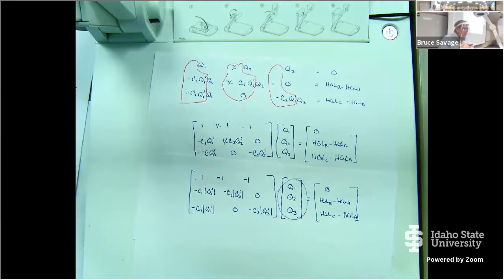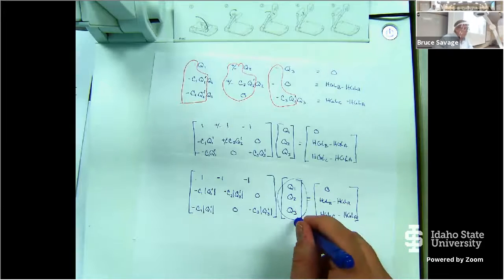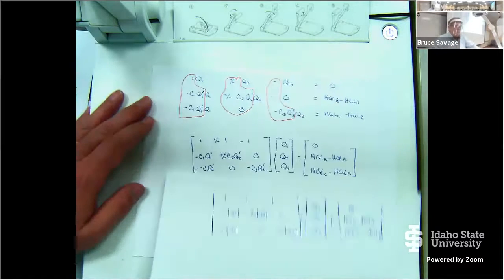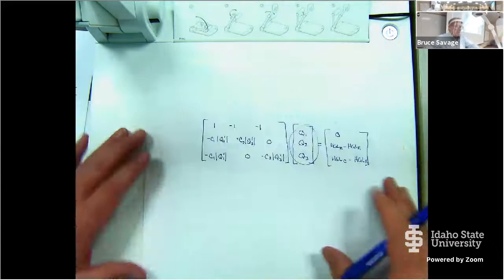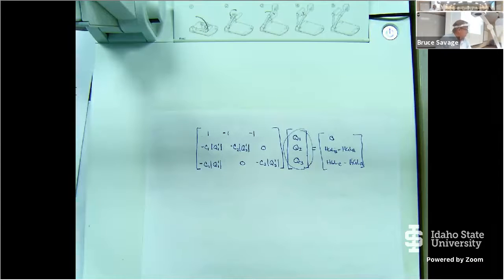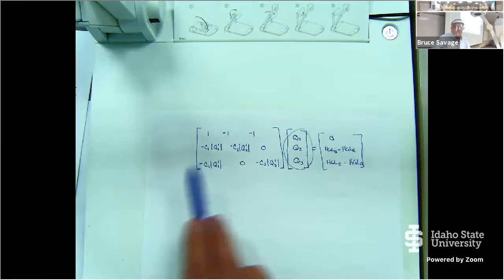It's a guess, and then we'll let the system solve it for us. So we take a guess. Q1 is equal to some value. Q2 and Q3 the same thing. Plug it into our equation, solve for Q1, Q2, and Q3. So plug it into our matrix and then we solve over and over. So this is the matrix that we're dealing with now again. And we're just going to iterate now as we solve for Q1, Q2, and Q3 and keep updating those as the new values. Now there's one little caveat, and we're not going to have time today to go through it, and I'll talk about that on Friday then, okay? But this is the procedure that we go through.